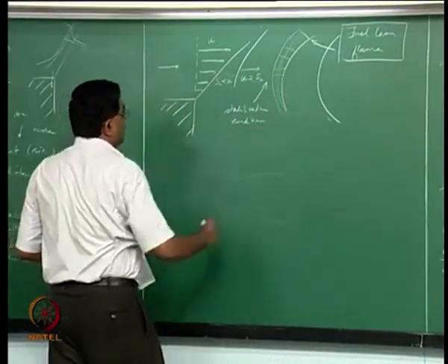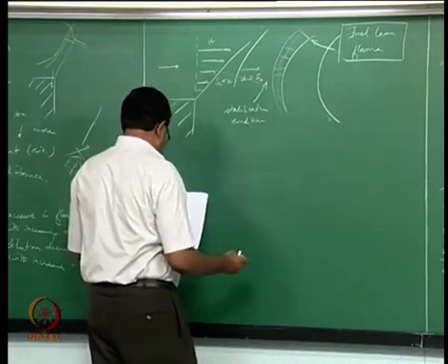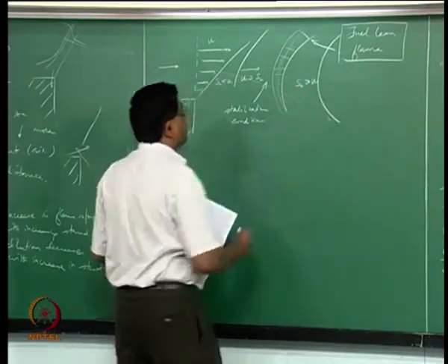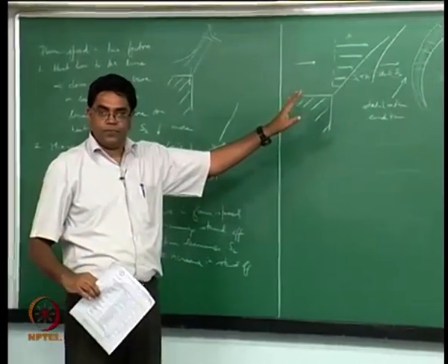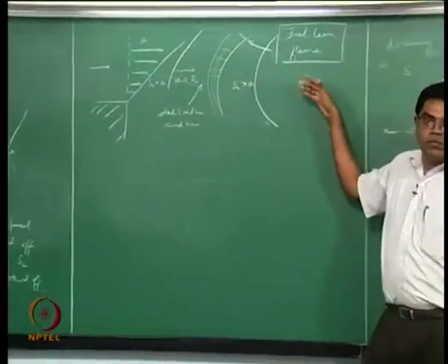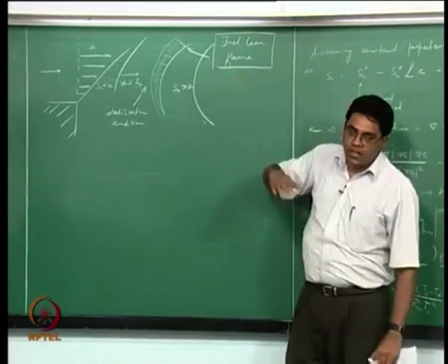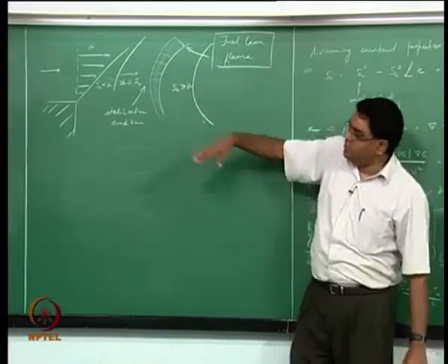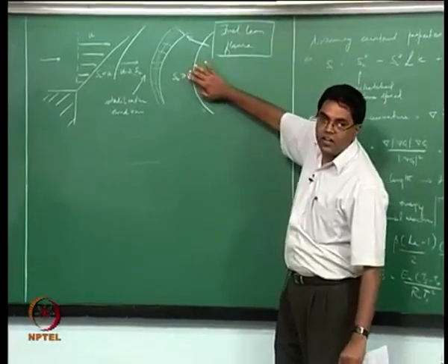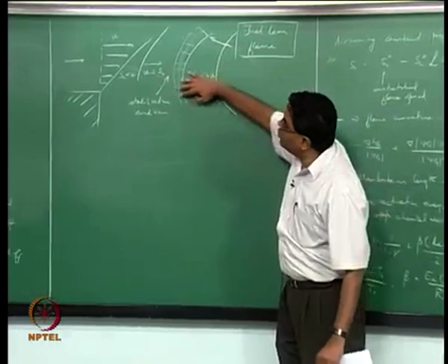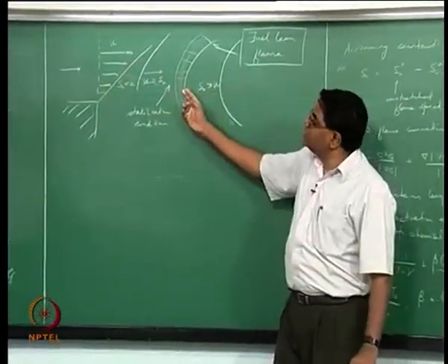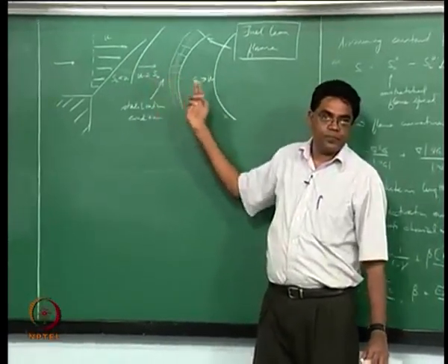So you can have a flame over here, but in this case the SL actually now becomes greater than U because you don't have too much of a heat loss effect, and therefore it has a tendency to move upstream. You now have a larger flame because the reactants have fanned out and they have less heat loss, and they have a tendency to move against a linearly decreasing velocity until you reach a matching point.